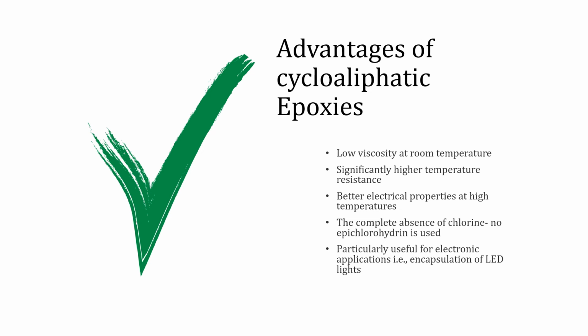Other features include low dielectric constant, great weather resistance, and a high glass transition temperature (Tg), which are really important. This type of epoxy resin cures under UV light and under heat conditions. As aromaticity is not present in these materials as it is in bisphenol A and bisphenol F resins, the UV stability is considerably improved. Overall, the benefits of cycloaliphatic epoxies can be summarized as their improved weatherability, significant water and moisture tolerance, better chemical resistance, and lower viscosities.